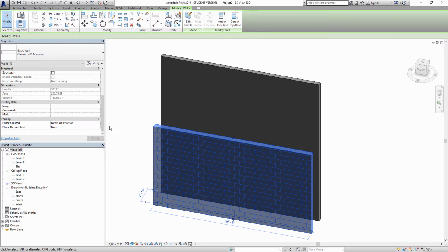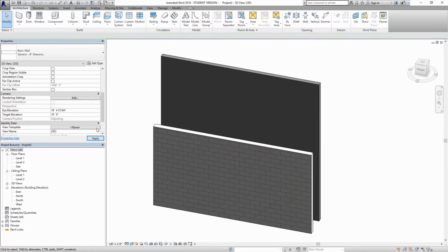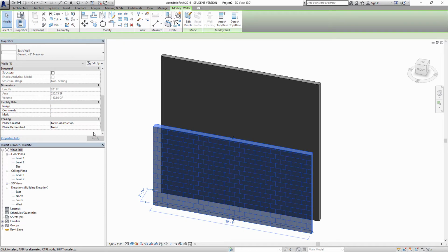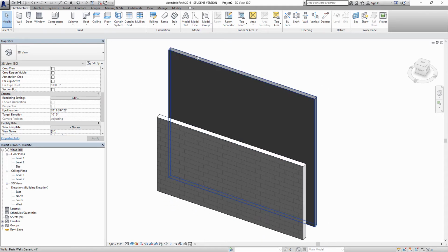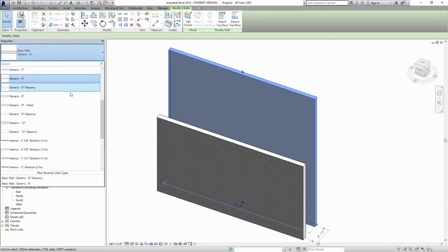If I was doing an existing project, I could say that this wall already exists, and later I could define if it needs to be demolished or if it will remain. I can also tell it that it comes in different project phases. So I could say it's going to come in project phase 1, 2, 3, and so down the line. And that will just help create a different series of drawings that will give different appearance for walls being built in any particular time.